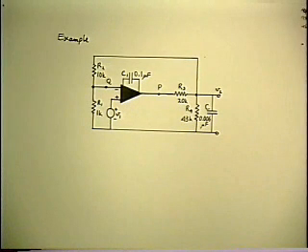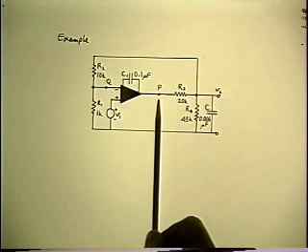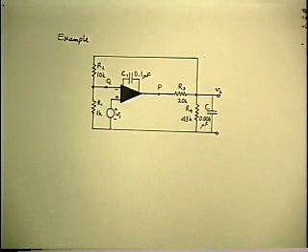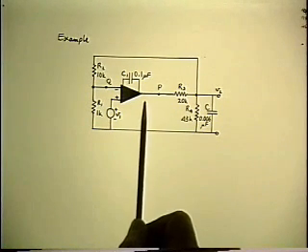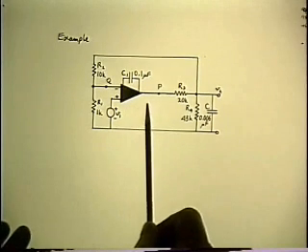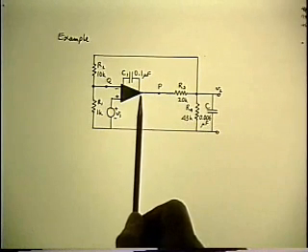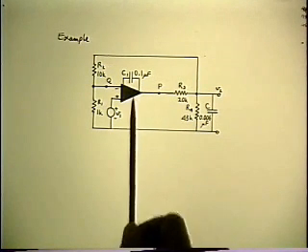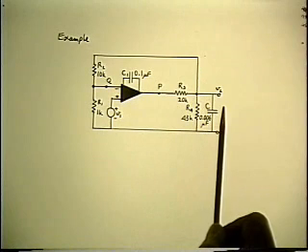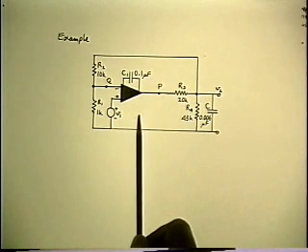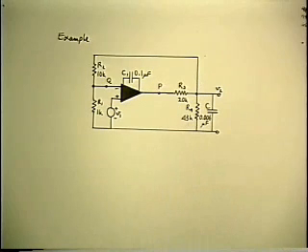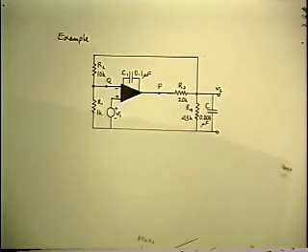I said earlier on, in justifying the selection of this operating point, I said the data sheet says the output impedance is very low, a few hundred ohms. I neglected to say the data sheet gives it at only one frequency. So maybe that's the culprit. So what I did was I made an independent measurement of the output impedance of the op amp. And I can calculate the Z1 looking in the other direction. So using my measurements of Z2, dividing them by Z1, I can actually predict what the ratio Z2 over Z1 is. And it's this.